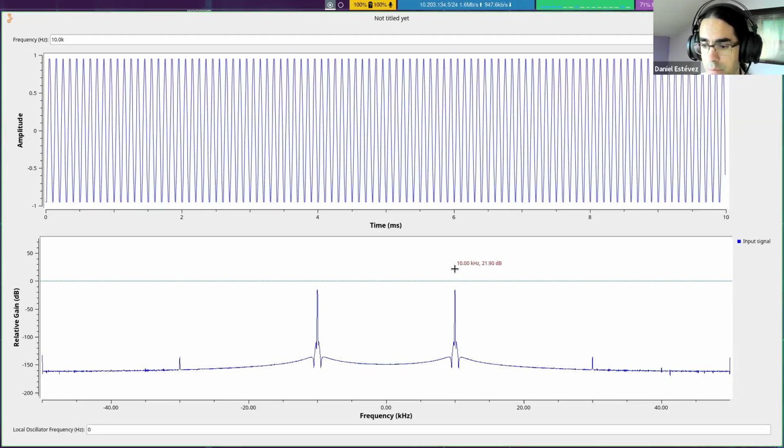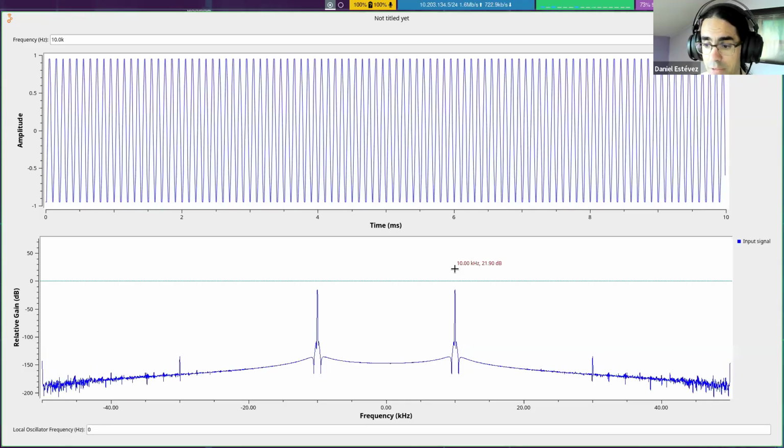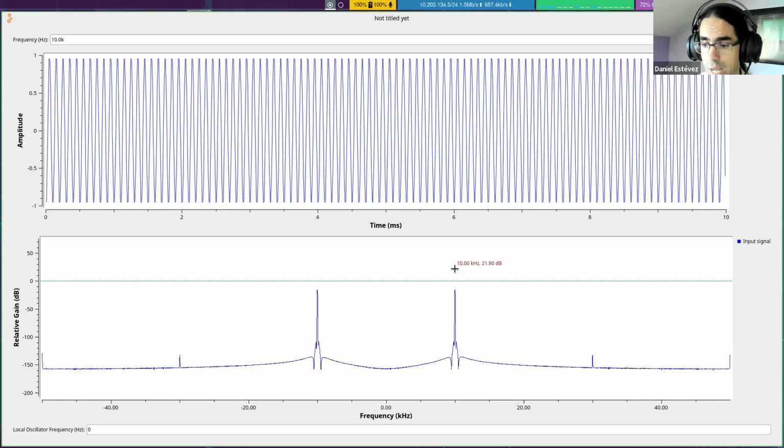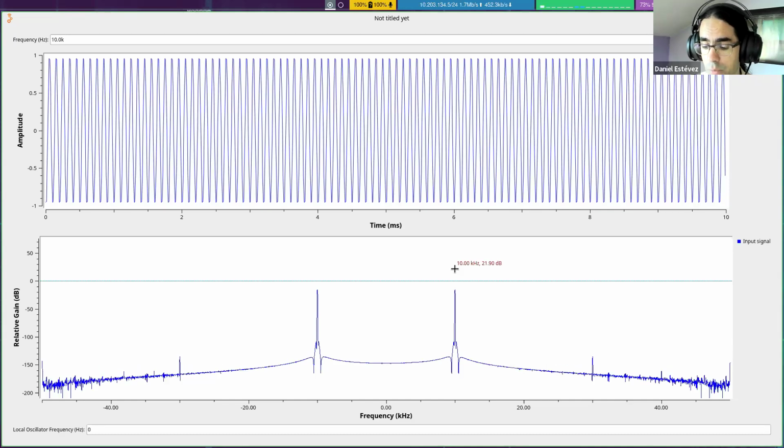And that's inconvenient because if you have a system, it's prepared to work with signals at a given nominal frequency. If things have been shifted in frequency because of this Doppler effect, we need to correct it. We need to apply the opposite frequency shift. So that's another example of why shifting signals in frequency is useful.